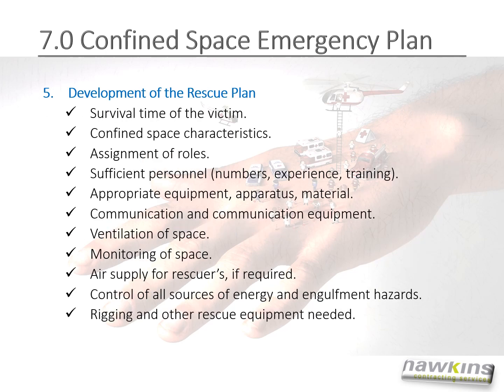And fifth is the development of the rescue plan. Consider survival time of the victim, confined space characteristics, assignment of roles, sufficient personnel, numbers, experience, and training, appropriate equipment, apparatus, and materials, communication and communication equipment, ventilation of space, monitoring of space, air supply for rescuers if required, control of all sources of energy and engulfment hazards, and rigging and other rescue equipment that might be needed.